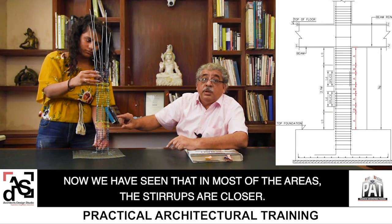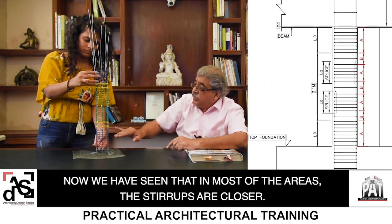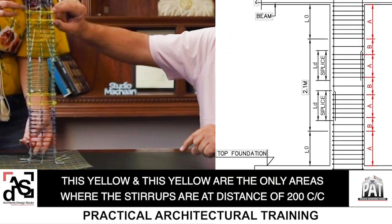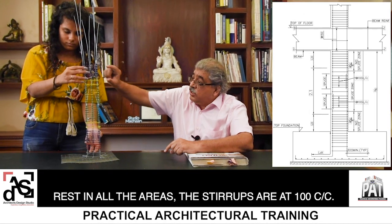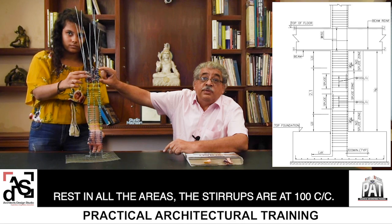Now we have seen that in most of the areas the stirrups are closed. This yellow and this yellow is the only area where the stirrup is at a distance of 200 center to center. Rest in all areas the stirrup is at 100 center to center.